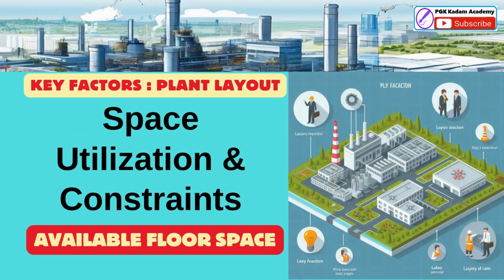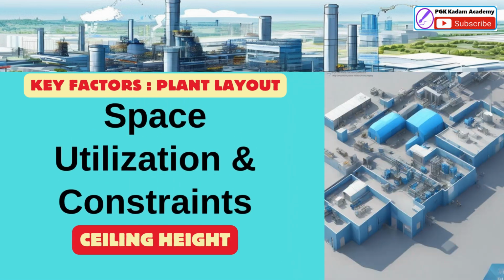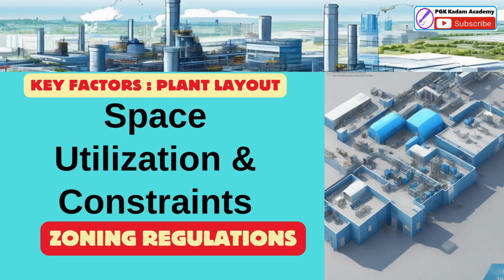Next factor is about space utilization and its constraints. Here it covers available floor space. Assess the total available area and any layout constraints imposed by the building structure. Ceiling height. Consider vertical space for equipment, storage, and material handling systems. Expansion plans. Allow for future growth and potential layout changes in the initial design. Zoning regulations. Ensure compliance with local land use and zoning requirements when planning the layout.